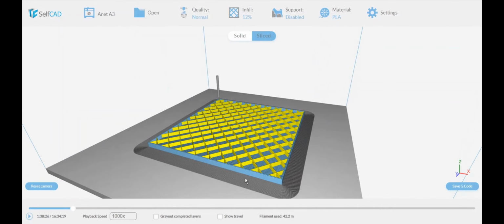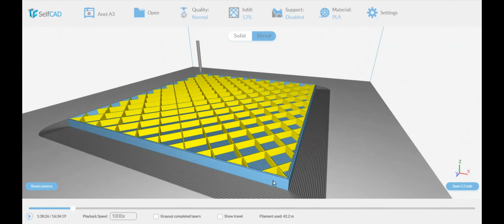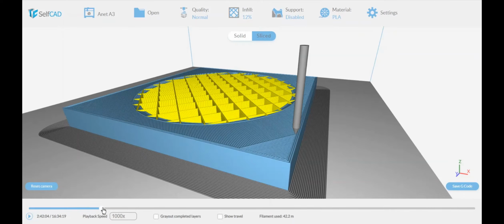Okay, so now we start moving up. We have a thickness that is called a shell. We already discussed adhesion, which is something to be removed later, to make it stick to the plate. Then we have a thickness for the outside, that's called a shell. And then we have to decide what we do with the inside. This is where we have the infill. If I have no infill, this will be empty, a simple void. And if we do more like this, it starts going over here.